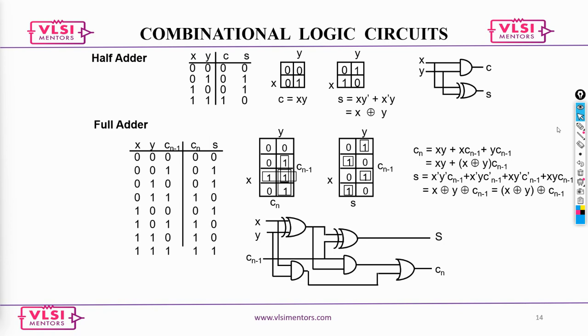One is basically the half adder. Now, a half adder has two inputs, and then you will have two outputs: one is sum, and another one is carry. If you have to realize the circuit, the sum is exactly, if you try to see which gate is going to give you this, it is an XOR.